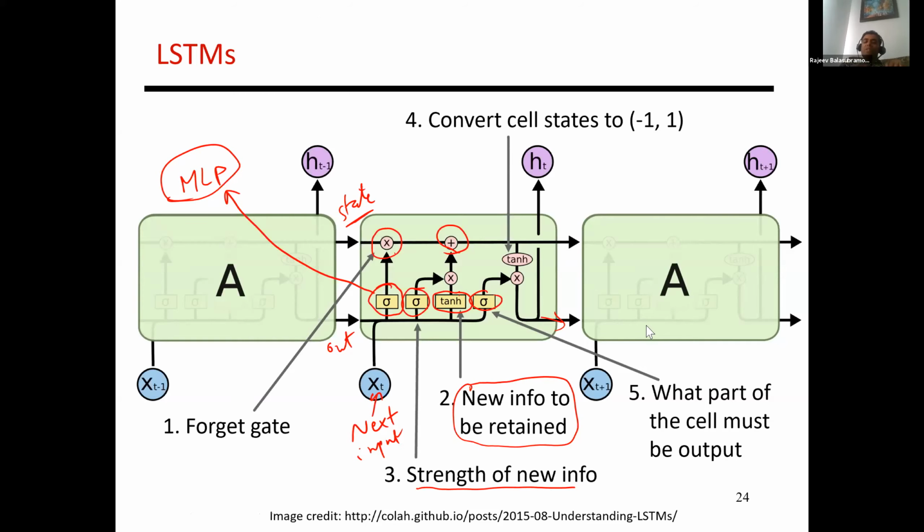So there's a question about DNNs claiming to solve dark silicon. That's not quite what I meant. What I meant is accelerators are one way to add value to chips, right? Because of dark silicon, I can't keep the whole chip active all the time. But if my chip was a collection of different accelerators, let's say that there's a sorting accelerator and then there's a deep network accelerator, there's a small chance that I'm going to use both at the same time, right?